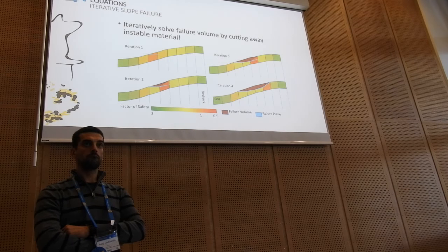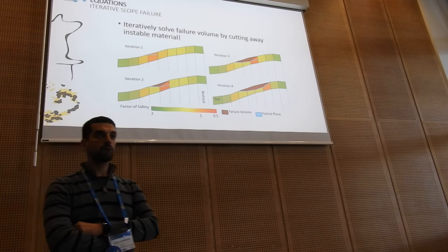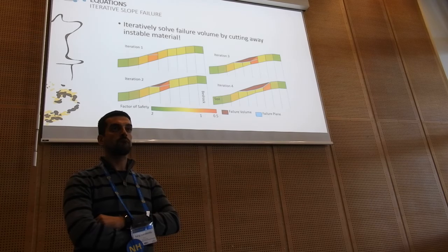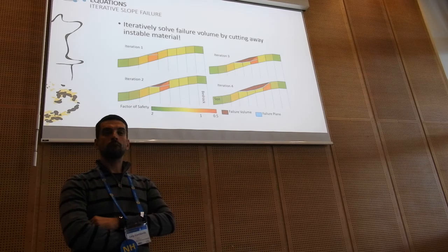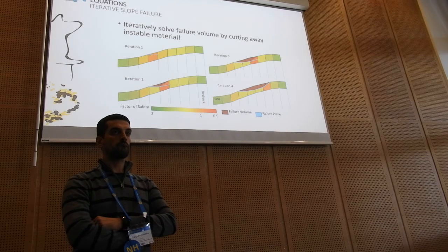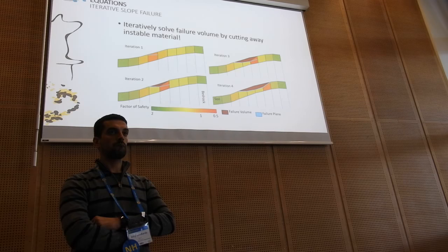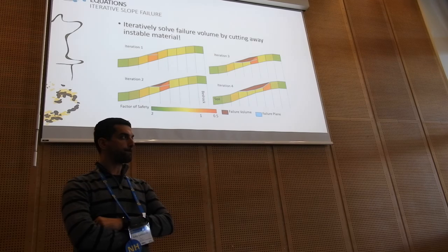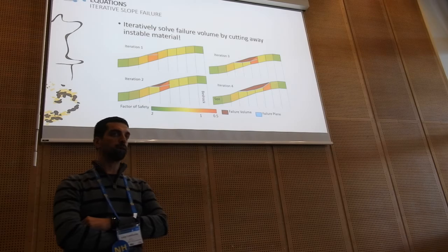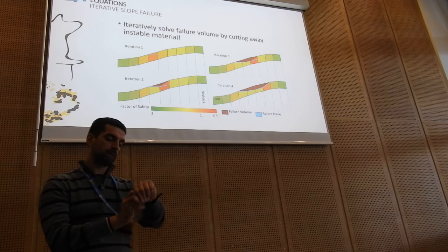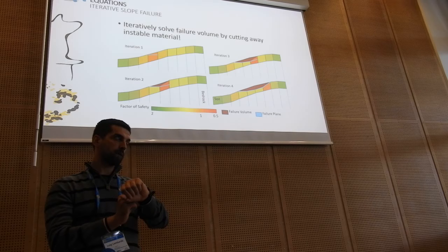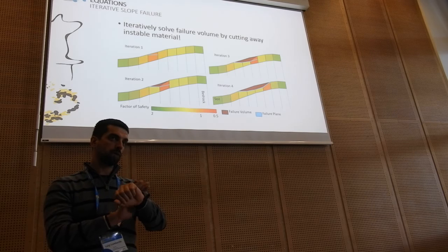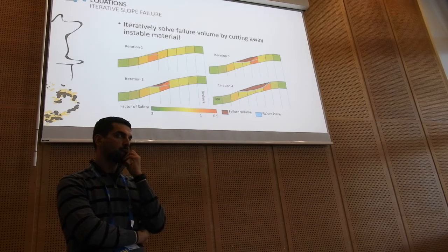Yes, on the tube we especially look for the interface between soil and bedrock to predict possible failures. So this will be very interesting for us to implement, to model these situations. Well, we initially started out like that. If you use the infinite slope model, typically you have only one potential failure plane, which is the bedrock interface with the soil.